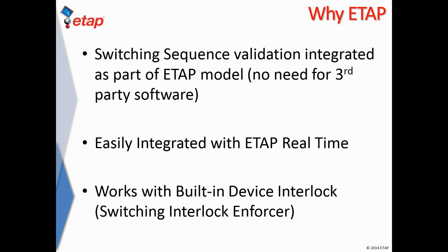All of that information can be imported as an ETAP real-time configuration, and your switching sequence can be validated in real time before the operator actually performs the sequence. So it's like a third or a triple check, right? You typically design your switching sequence, you test it using various methods, one of them being the ETAP SSM module. You perhaps hand it over to the operator, but with ETAP real time you have that extra layer of protection